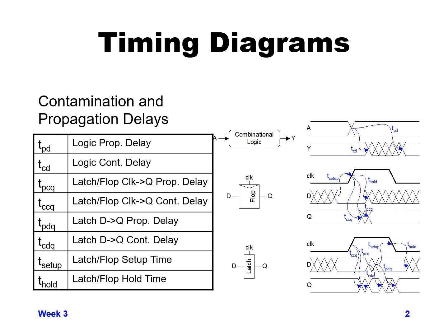Depending on how complex your logic is, you could have a propagation delay that is vastly different than the contamination delay. You could have a vast amount of time difference between those two, which will lead into interesting effects when we look in later slides at our timing and how fast we can run our clock.